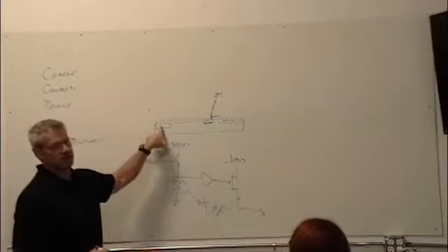But then you have to play games because the shift register is now exposed to light from the backside, so now you have to put down something on the backside to mask it so that it's not acting like a bunch of pixels too. Yeah. And generally what you'll do is you'll have a section off over here and a section off over here that are dark. So I can shift along this whole line and I should get black, black, black, black, black, black, black, data, black, black, black, black, black.